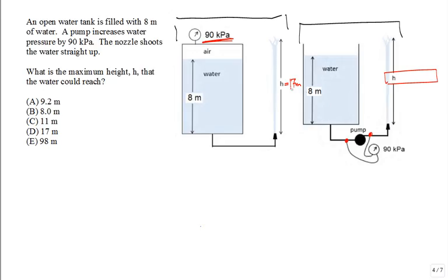And so now that really leads us to a modification of the Bernoulli's equation, so that we could include gains of mechanical energy due to pumps or other devices. Before we ran the equation from maybe state 1 to state 4. Here we're going to run it 1 to 4, but that goes through this pump.